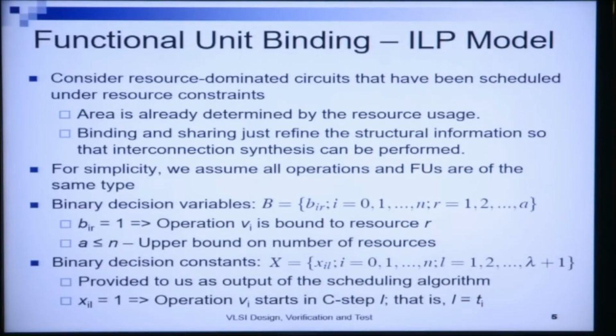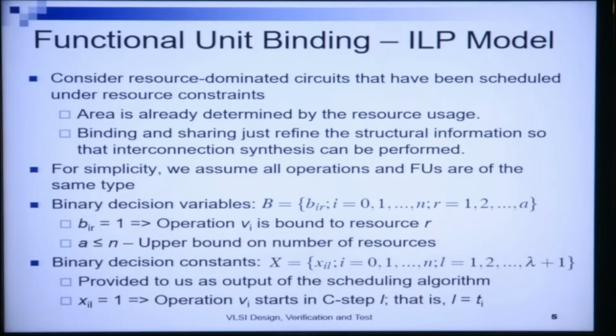Now, with this definition, we first characterize the resource sharing and binding problem with a simple case. Let us consider resource dominated circuits which have been scheduled under resource constraints. So, we have done resource constraint scheduling during my schedule step. Therefore, the area is already determined by the resource usage, and I know the number of functional units that will be required. Binding and sharing in this case will just be to refine the structural information so that the interconnection synthesis can be performed.